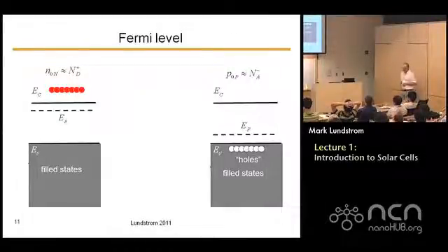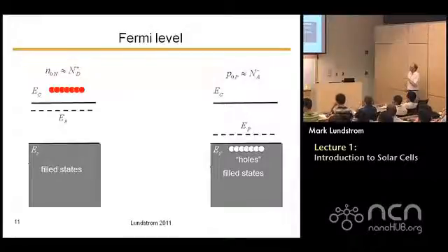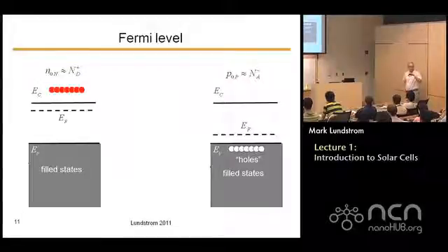So now the concept of a Fermi level. Those of you that have been with me for the previous lectures know all about Fermi levels and Fermi functions. But for those of you that are brand new to this lecture, let me remind you of what it is. We think of the Fermi level as telling us how the states are filled up. You can think of it as a liquid water level. Things below the level are filled, things above are empty. So if the Fermi level is up near the conduction band, it means that at T equals 0, there's an abrupt drop-off.